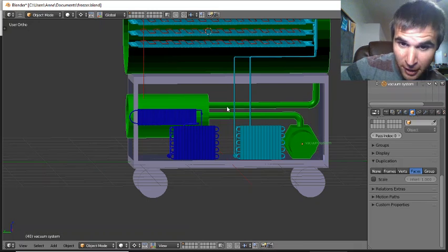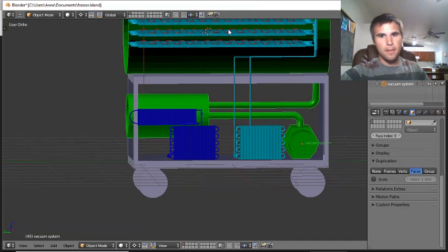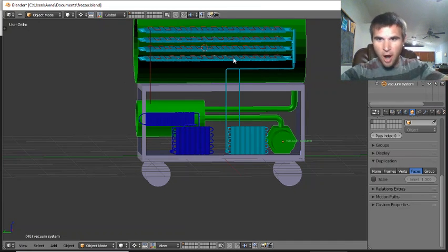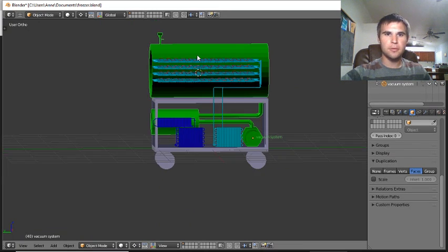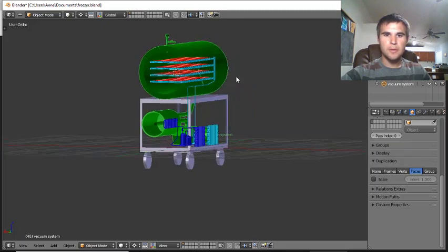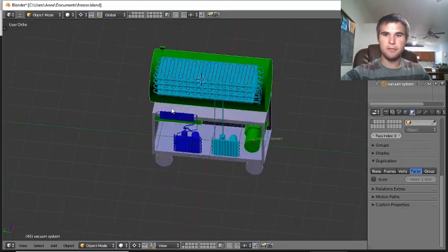So that's stupid. Yeah. So if you put a valve here, you could shut the system off mid freeze dry, because the vacuum up here, as the product sublimates and off-gases, the pressure will constantly be rising, but you're only talking about a few minutes. So by the time you finish draining the trap and got the whole system back up, you probably wouldn't have lost a huge amount of vacuum, or at least not enough to have done the problem. So that's my little design. You can make it as big or as small as you want, but I think bigger is better for us.